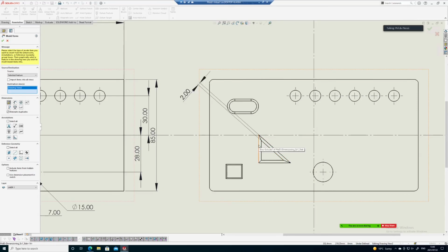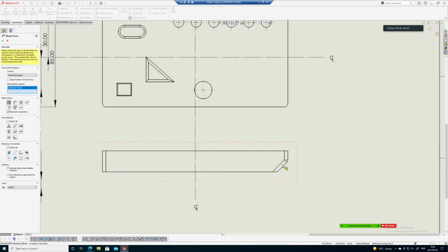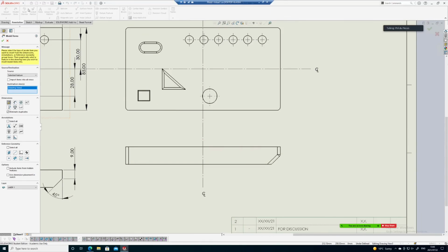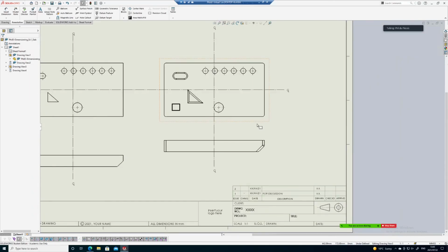These lines at the outside here are not actually geometry. They're geometric features, but they're not shape features. You dimension them differently. So we're going to go through that. At the bottom here as well, how to dimension those things if we don't use that button first, which I think we can still use as well. We'll go through all of that, and then what things not to dimension if you ever do need to do manual dimensioning.